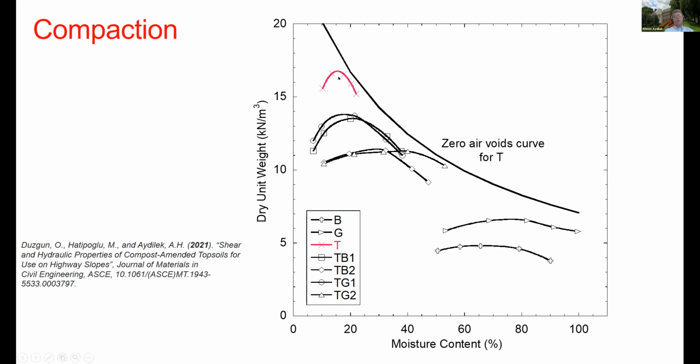So topsoil, yes, we are not building an embankment with the topsoil, but that meets that requirement, versus the other ones that are way below it. When they compact these systems in the field, they don't really apply any type of compaction forces. They apply a little bit of tamping force, so they locate the particles, but with the intrusion of different construction equipment and the vibrations produced by them, the soil is inevitably compacted to a certain degree.